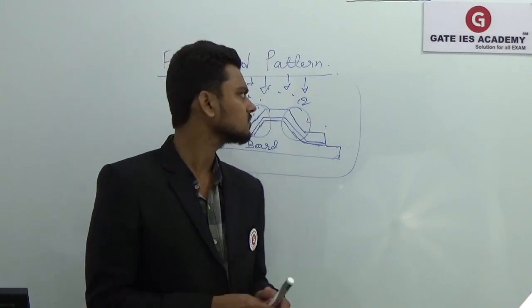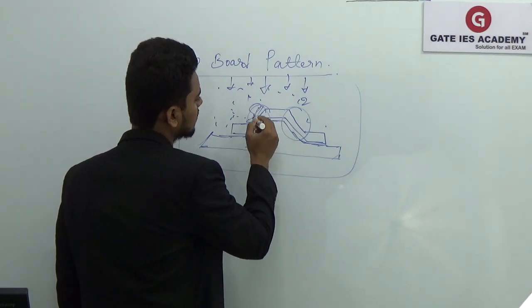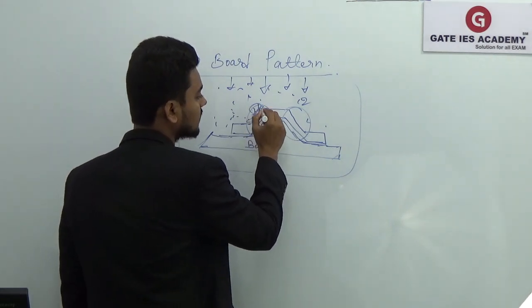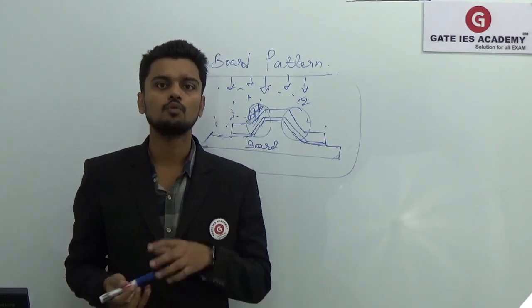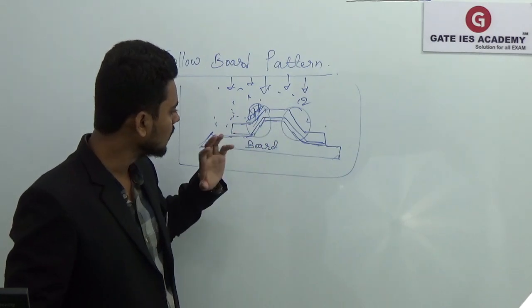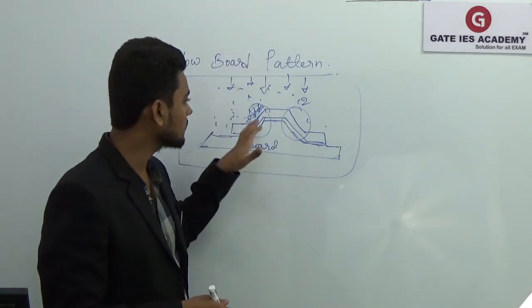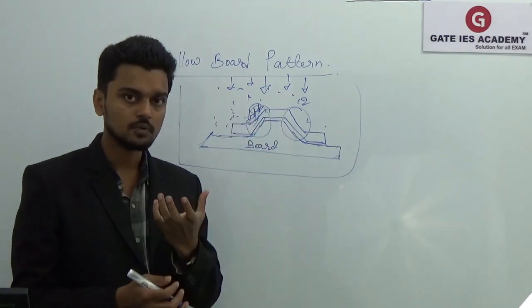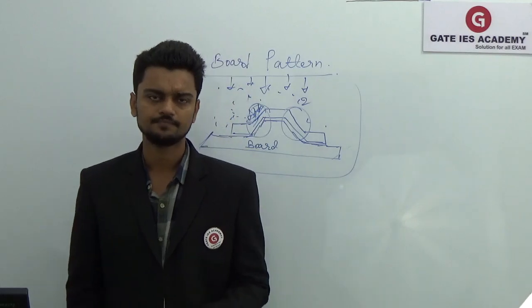Because the sand which is near to that weak section will provide the required strength while making the cope part. So it is not necessary to keep that board in making the cope part. The sand below that pattern, which is in the drag, will give you the required strength.